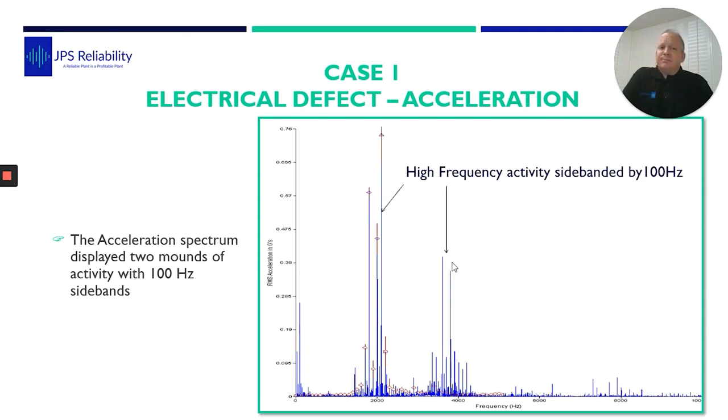So I said to them, well, I've got an electrical defect. It's picking up a vibration. You can touch it and feel it, as if the motor was bumping, missing a heartbeat. So it's not mechanical, your bearings are okay, something electrical is causing the problem, some connection, and the recommendation was to check all the terminations.